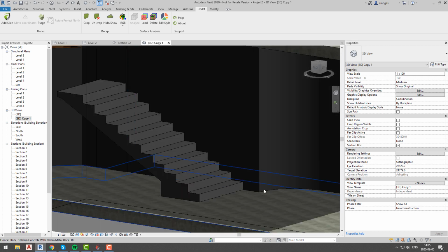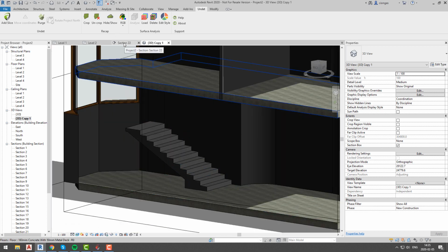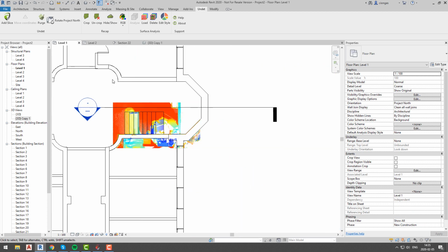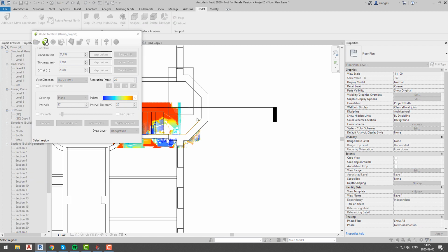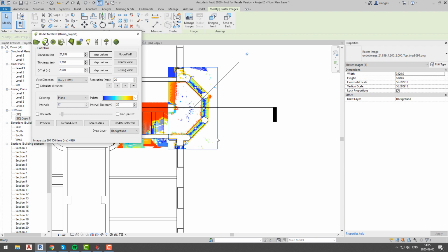Using Model in Place we will model stairs landing which is in between levels. So we will follow same workflow, by creating small dynamic image, following landing outline and extruding it to correct level and thickness while in section view.